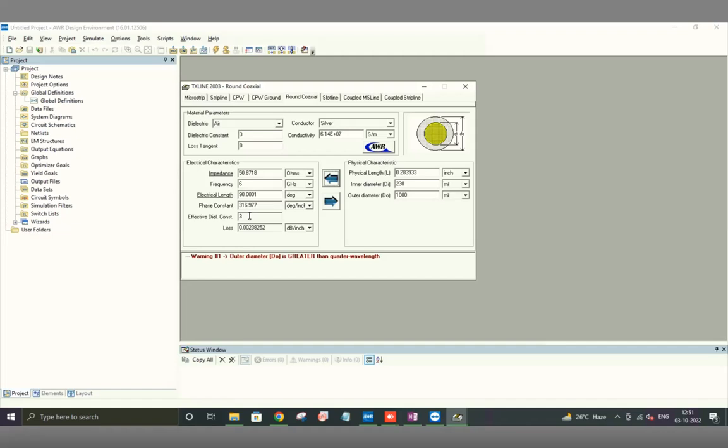That will affect how the impedance, coming from the capacitance per unit length, will change as you change the dielectric of the system. Because now the total dielectric is a combination of both the dielectric you're changing and air. Usually the other part is air, right, or vacuum.